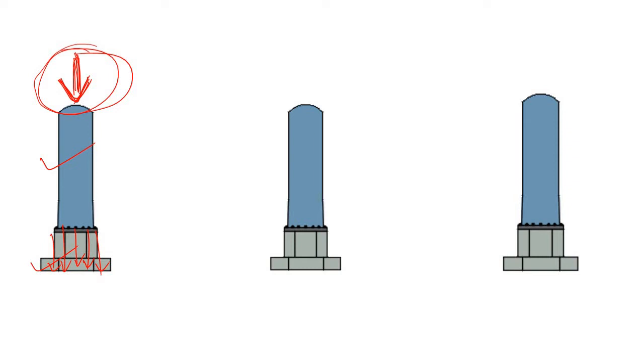Okay, so why do we need to use anchorage? Let's say that instead of only gravity load, you also have some lateral load, because of wind, or maybe an earthquake load, or some piping load. You will also have some lateral load like this. If you do not fix these two parts at this location, what will happen?